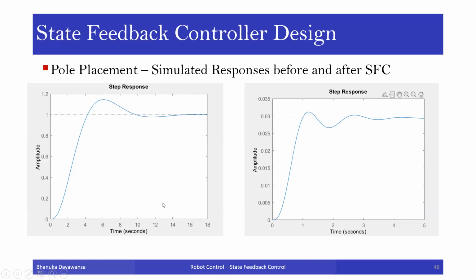Settling time is around 14 seconds, but here it is settling at around 4 seconds. It's actually a very zoomed out version. It's settling at around 4 seconds at 0.03. Small offset is there, right? Small offsets like 0.03 millimeters, that's not very negligible. That much settling time is obtained in 4 seconds. That's very impressive, to be honest, for the system to obtain that type of stability in that small time.